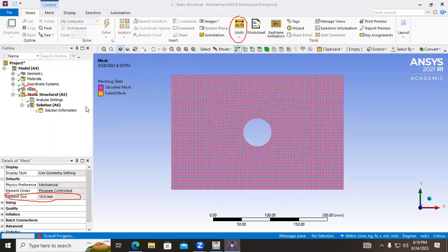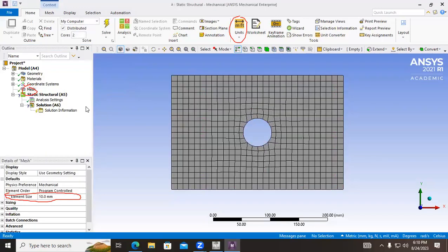All right. Any questions on the mesh? Everyone able to generate mesh? Okay. Yeah. Smaller the mesh, the more accurate. Exactly. Yes. For this one, it's not going to matter too much because it's really simple. But for the more complicated cases, finding the correct mesh element size is something that's really important. All right. Any other questions on the mesh?